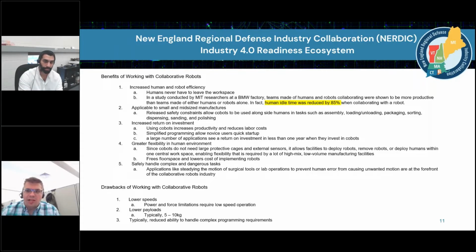You can very easily enter the cell or the work area of the robot and remove the faulty piece, or perform some other corrective action without having to bring the robot to a complete program halt and restart the program. This also then allows, of course, immediate collaboration of handing parts to a robot, or having a robot unload parts, say from a machine, directly into a person's work area, where they can then immediately pick them up and keep working without any sort of a timed interchange.